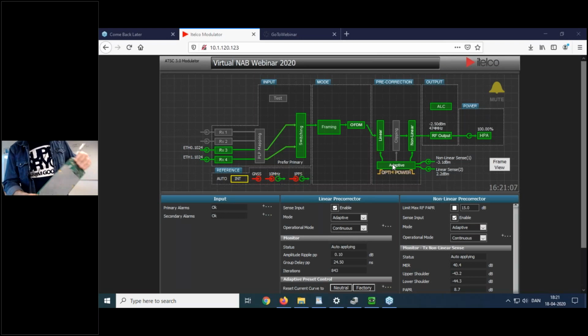This is how it looks like. As I said, this is the third generation. And just for your information, I think we are probably today above a total of 40,000 installed base of these around the world. So the board, exactly as you said, Chuck, is a 16-layer board. We have 4 gigabit Ethernet ports here. These ports all have individual MAC addresses because some operators consider redundancy feed over IP. The endpoint really needs to be an individual MAC address.